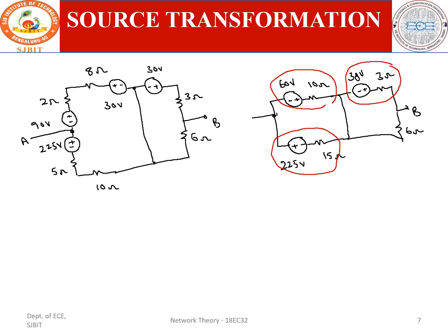So after converting, you can write like this. So this is the point A. This is the point A, the same point. Again you convert this. So current source, you can write a direction like this, and this resistance you have to write. This is your 10 ohm. This is I is equal to V by R. This is 6 amps.